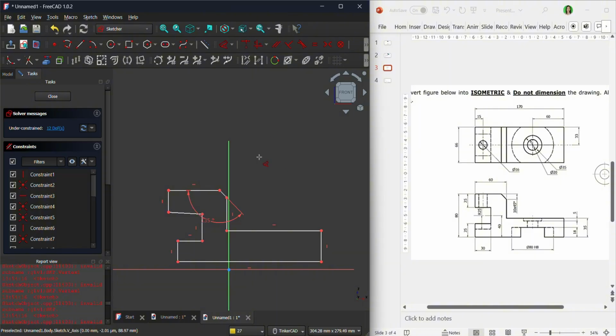We will recheck. Then, as I mentioned here, make sure that you are doing this measurement, not the other one. Okay, this one is 11, but that is not what we would like to add. It's not the measurement, okay? Remember that this one is 10 millimeters, and the direction of the dimension line is like this, not diagonal.